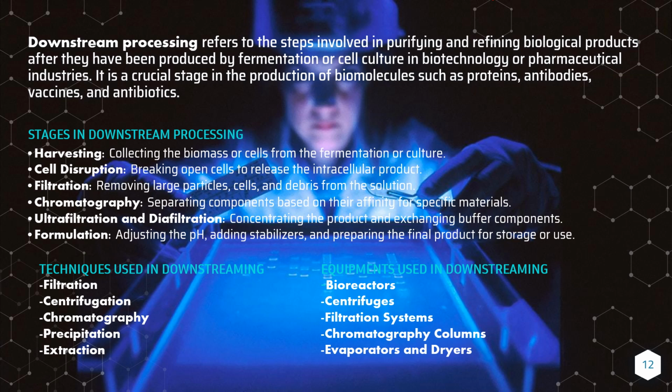Our next one is diafiltration. Diafiltration is a modification of ultrafiltration that involves the continuous addition of fresh solvents or buffer to the retentate to replace permeating components. It is used to improve product purity by removing small molecular weight impurities and exchanging buffer components.